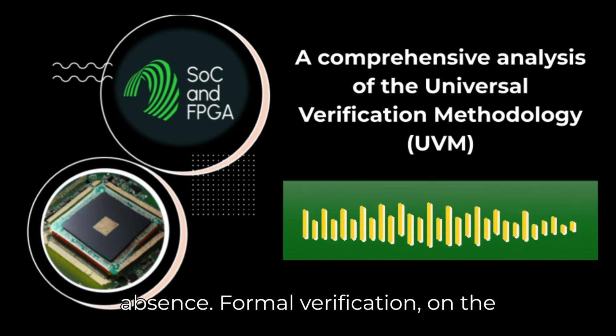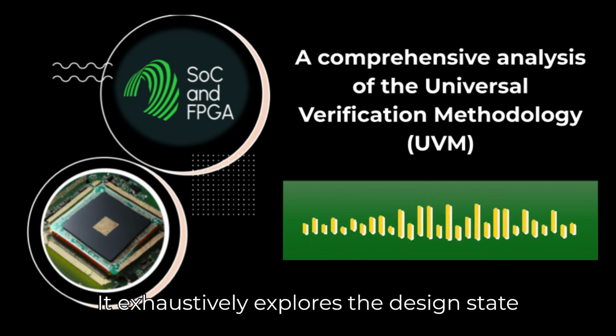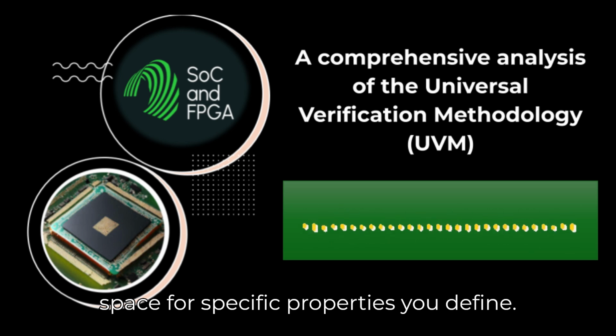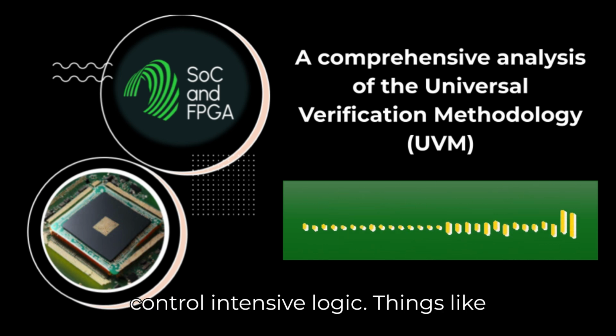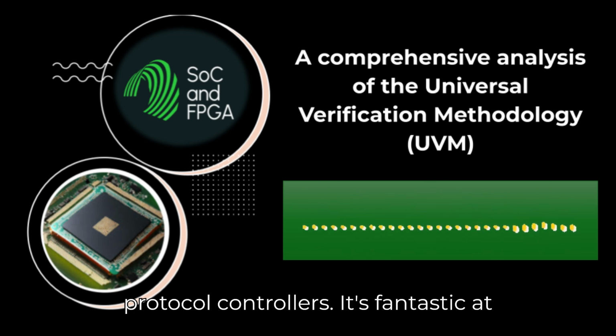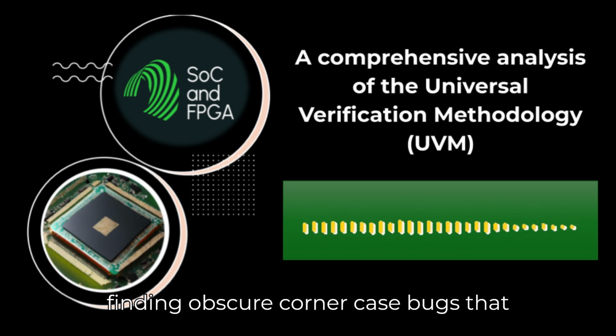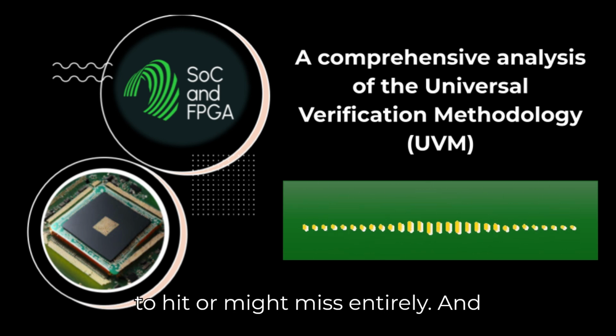Formal verification, on the other hand, uses mathematical techniques. It exhaustively explores the design state space for specific properties you define. What's formal good for? It excels at control-intensive logic. Things like arbiters, complex state machines, protocol controllers. It's fantastic at finding obscure corner case bugs that simulation might take billions of cycles to hit or might miss